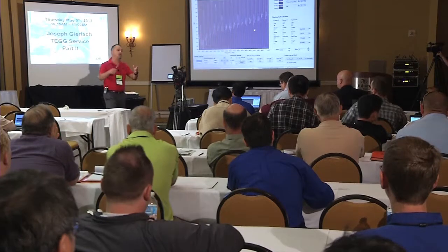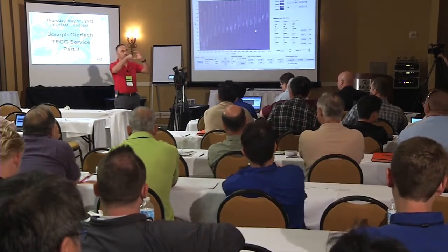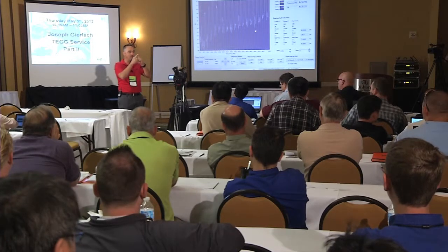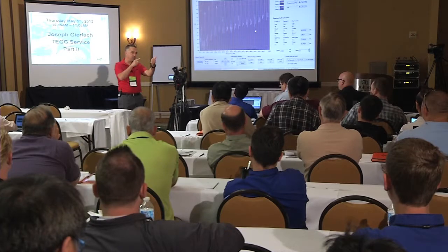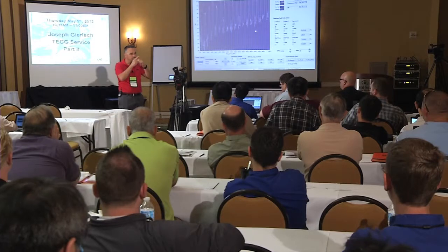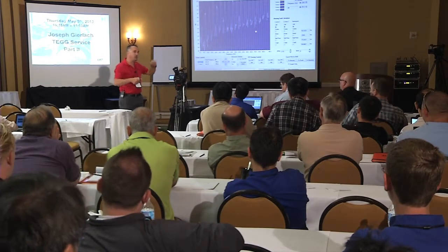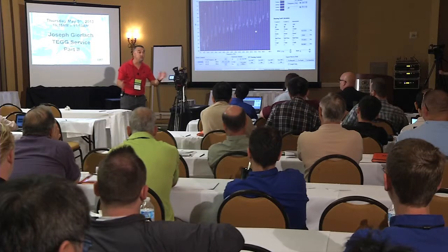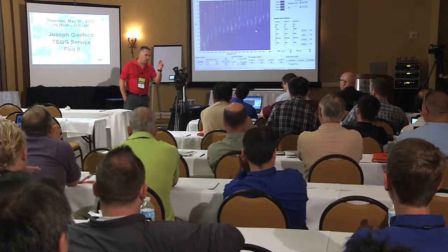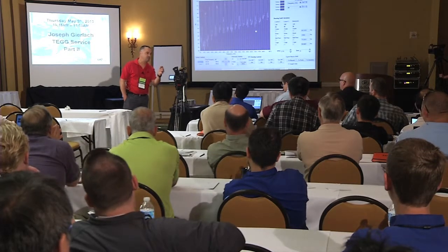See, usually, if you take a regular contactor, you have a stationary part of the armature and you have a movable part, right? And it closes and the contacts make. If they're sitting there chattering, they're doing what? They're going to be vibrating, number one, but they're also going to be producing arcs. So the vibration of the contacts can result in a 30 hertz harmonic. Does it do that always? No. But I have seen it where just the vibration and the looseness of that, the not making good contact surface, has produced a half frequency. More prevalent in stuff like transformers, but if you see it, you know it's not electrical is all I'm saying.